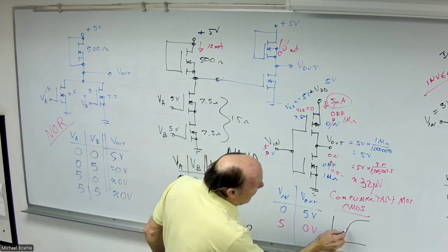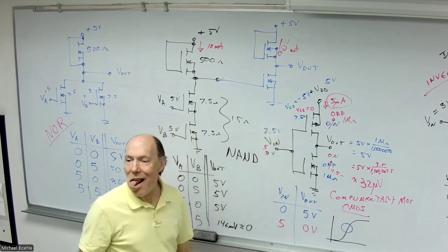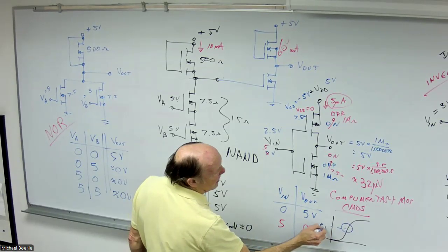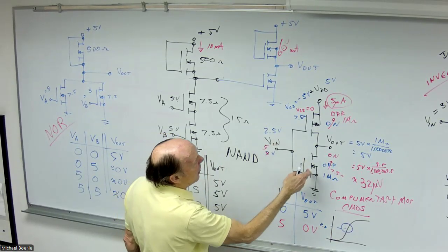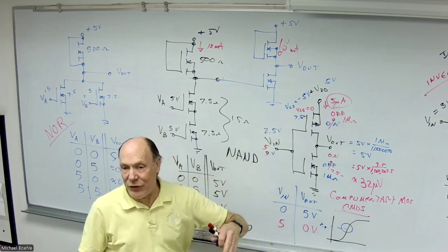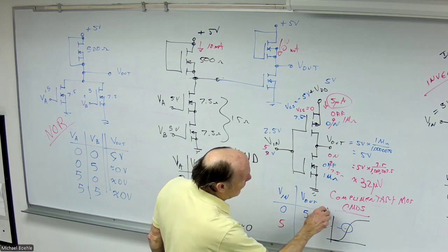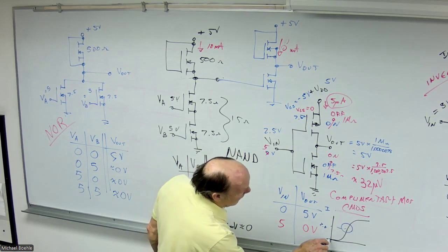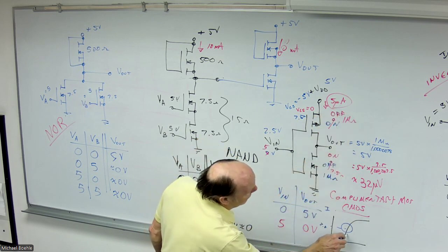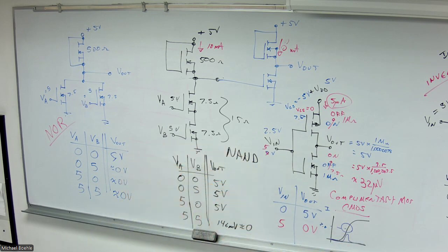And so during that very brief period of time, let's say we're at about 2.5 volts, then I'm just above the threshold here. 2.5 minus 5 is negative 2.5, just above the threshold there. So if we look at the current during that time frame, you'd have 0, or 5 microamps, and just a little bit during that transition until the other transistor turns on.